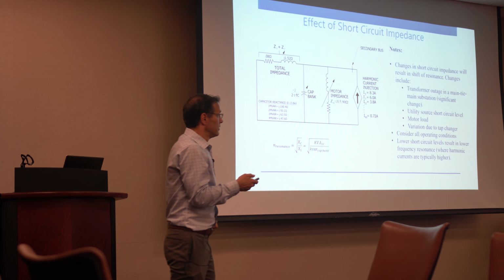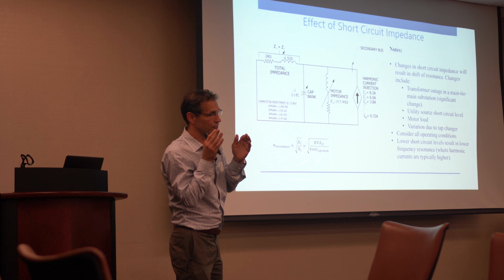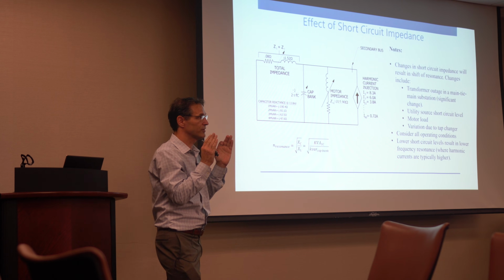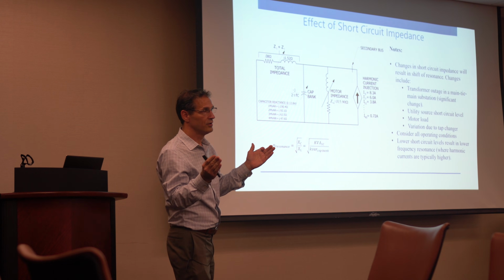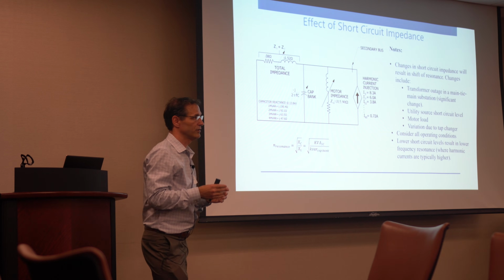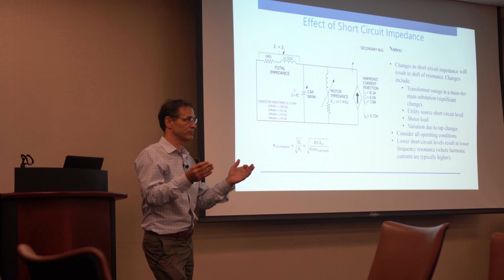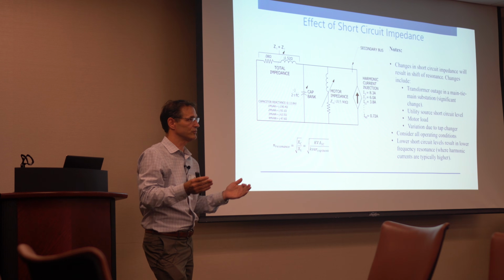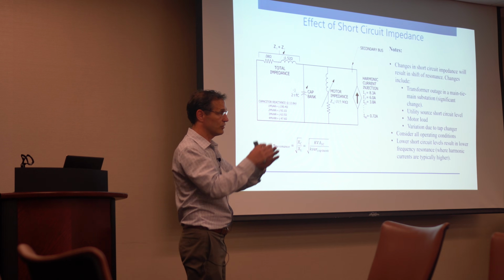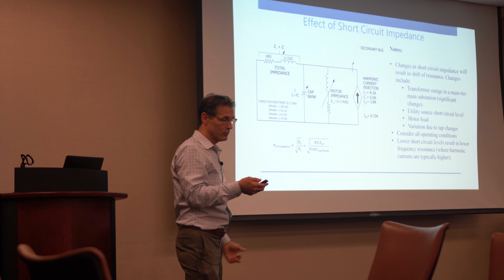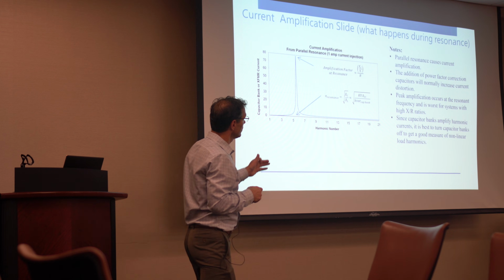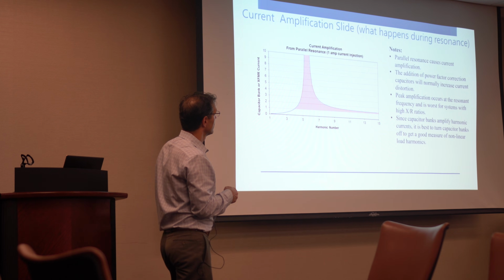So if you're the drive supplier and you've got the blinders on, you're not looking at the network as a whole, the drive is compliant, but the system is not. System designers have to be looking at the entire system, which includes the capacitors of the network, the cable capacitance, and all the drives. You have to look at the whole system as a whole. So current amplification is a problem.